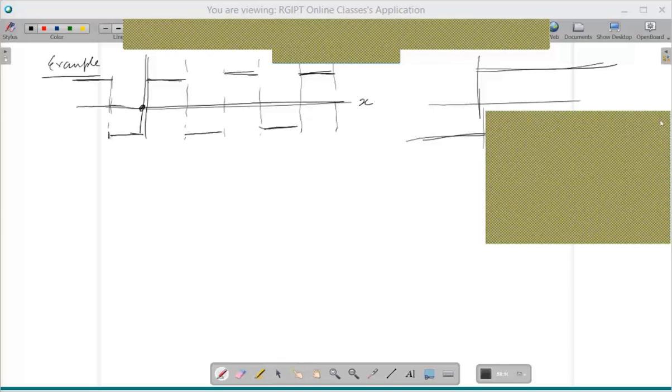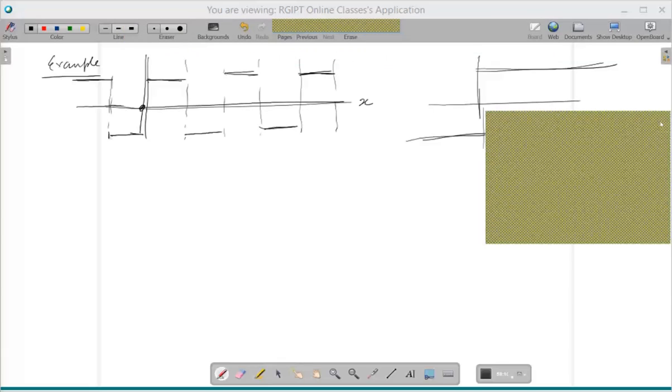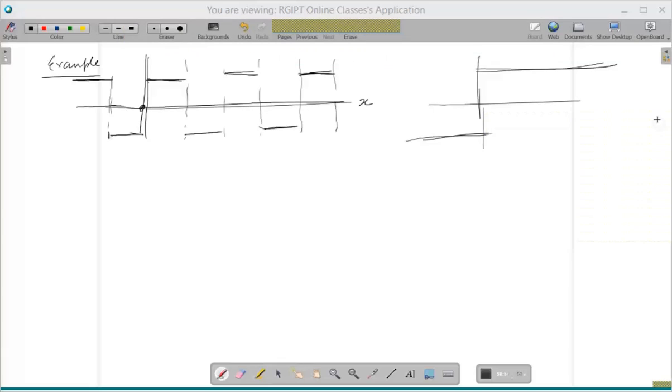Reactors. Yeah, plant control is one. Reactor analysis, exactly. Reactor RTD, exactly. That's what I was thinking. RTD, residence time distribution in chemical engineering: if you want to characterize a reactor, you give inputs which may look like this. If you know the response of the reactor to these kinds of inputs, you actually know a lot about the reactor, right?